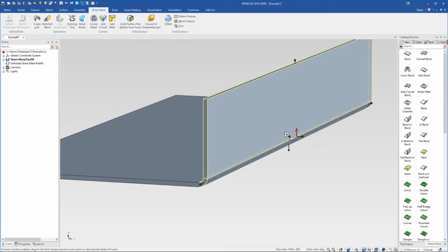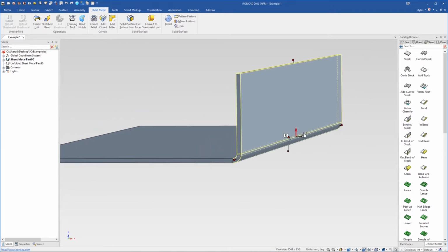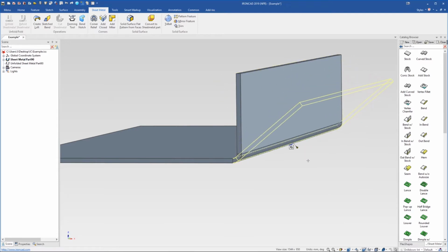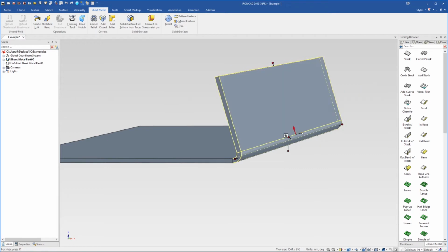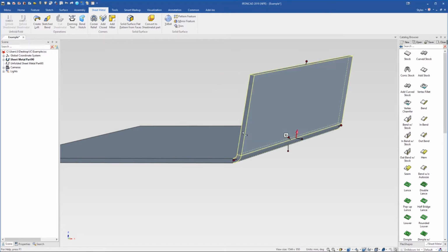You can also change the angle of the bend using these handles here. The handle on this side will change this side of the bend. The handle on this side will change this side. This can be pushed and pulled randomly depending on the angle you're looking for, or just to try out different angles, but it can also be precisely sized as well, just by right clicking and selecting Edit Angle. And then you can type in a specific angle. For example, we'll type 80 degrees, hit enter.